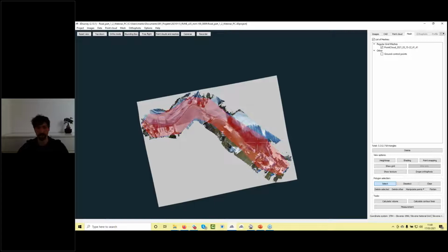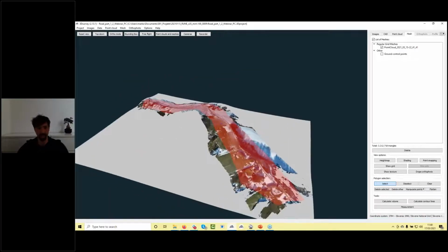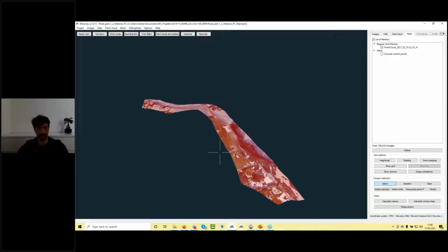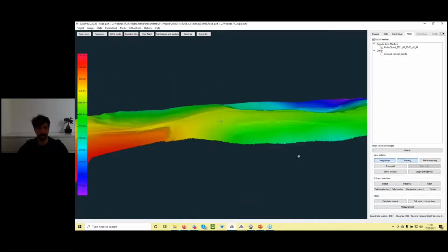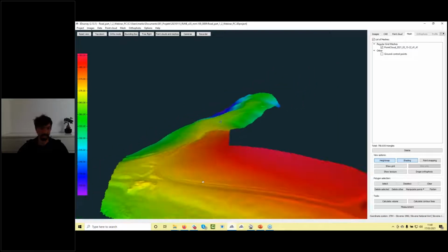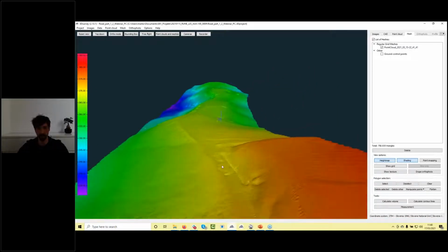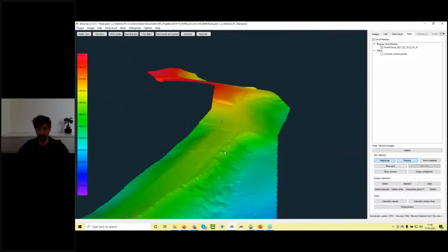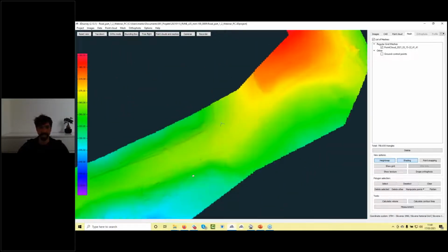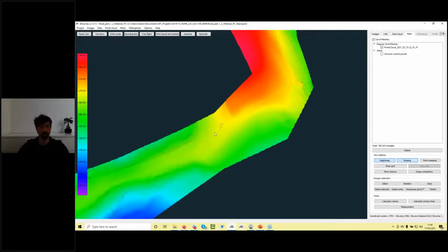Okay, right mouse to finish the selection, and now just like before, delete other, and immediately I have my area of interest, a really nice detailed digital surface model with the regular grid. Okay, cool. And this is already a nice basis for orthophoto calculation for this part.